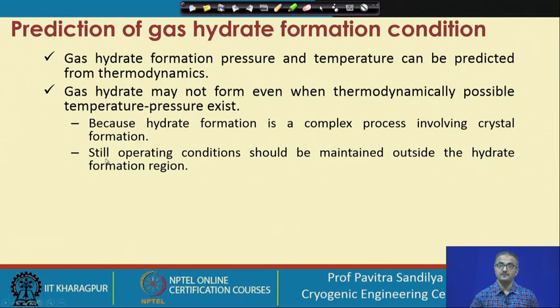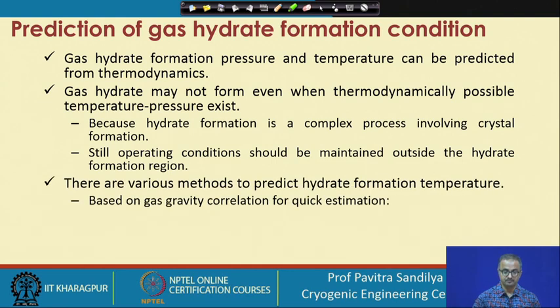So, even if we have the right temperature and pressure, we may find that the hydrate is not getting formed, but still the operating conditions have to be maintained outside the hydrate formation region to see to it that there is no chance of any hydrate formation.